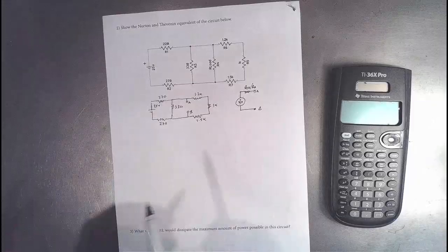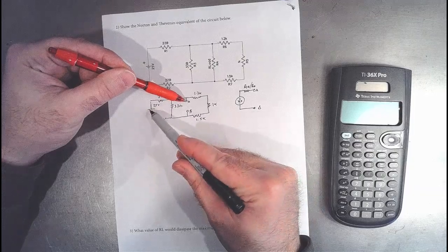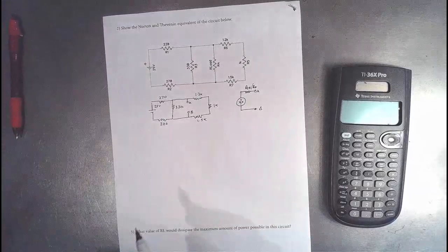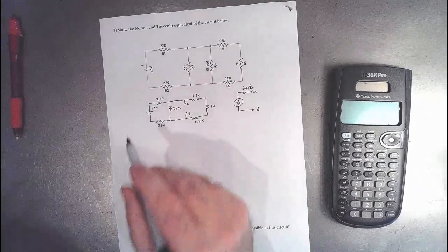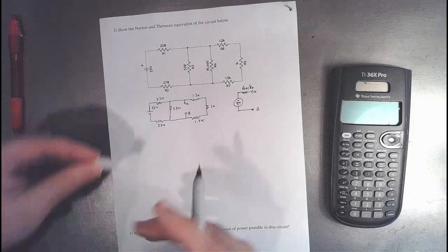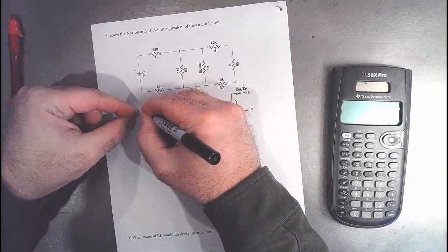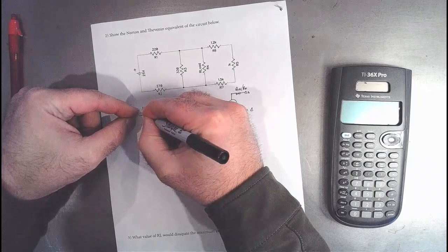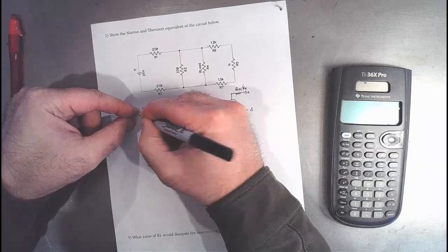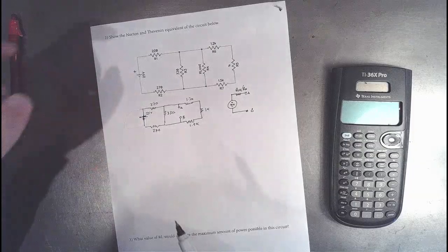So that means if I took an ohm meter and I placed it right here with the circuit turned off, what would it read? So first off, how do I turn off a voltage source? For a voltage source, I need to short it. So I'm going to try to do it without having to redraw this circuit. So I'm just going to put this little paper here. And you can see that I have shorted this voltage source right here. Okay, so the resistance across this thing is 0 ohms.